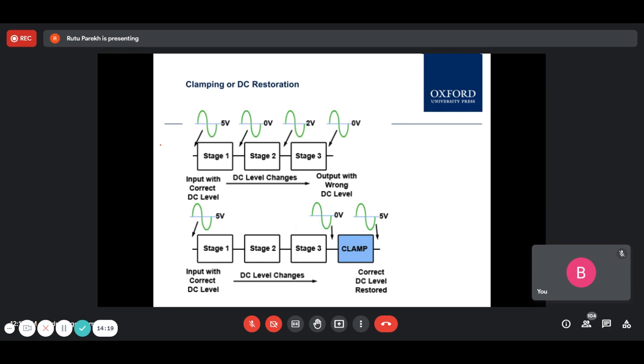Okay? Yes, ma'am. Yeah, so that bias we were giving for the small signal is the DC bias. In case of a diode, it is simple to understand that for a millivolt signal, you are giving some DC voltage so that the diode is operating and can process a little signal in millivolts. Whenever you are using a BJT, making an amplifier or filter or anything, all the circuits have a bias, and that is DC biasing. That is the DC signal we give to provide enough energy or operating conditions, in terms of voltage, to your signal so that it can be processed.